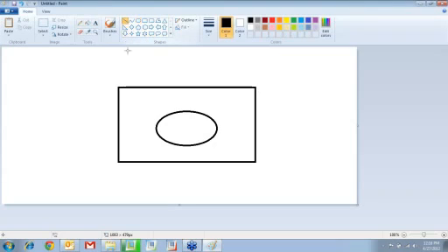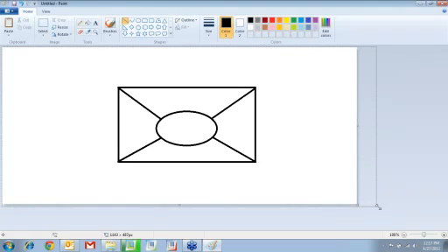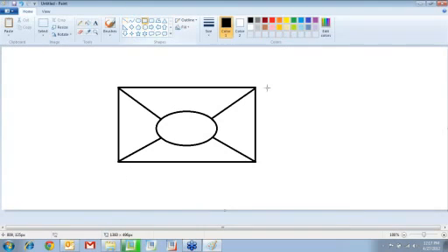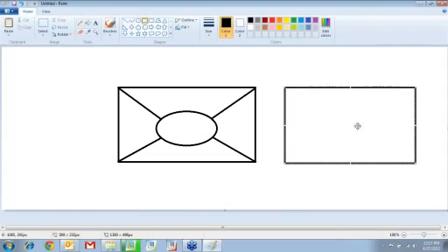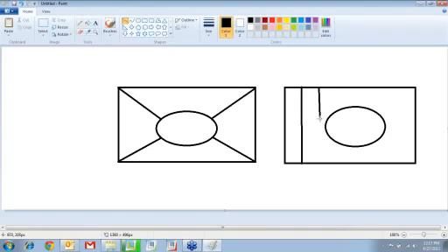Now, in a P-type FEA, you can create larger elements to solve for your answer. All right. Now, similarly, in an H-type FEA, if you had the same plate with a hole, you would have to create much smaller elements. Now, why is that so?